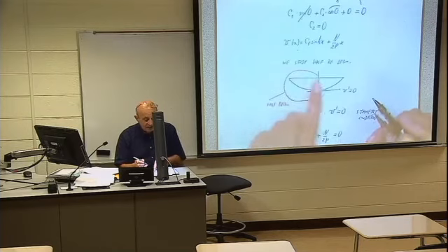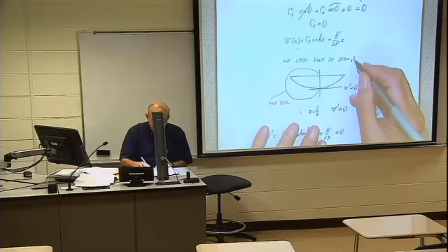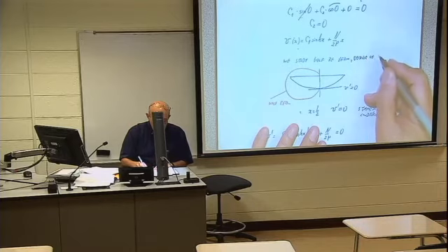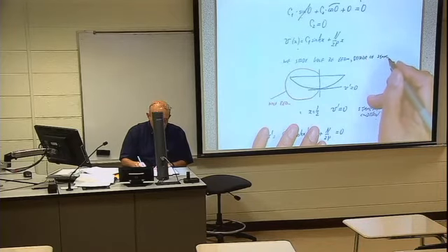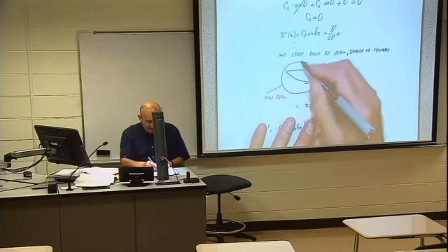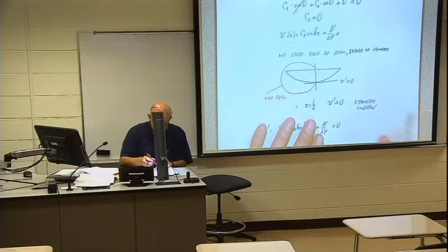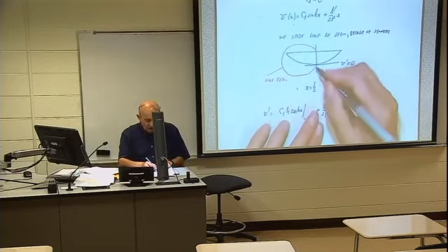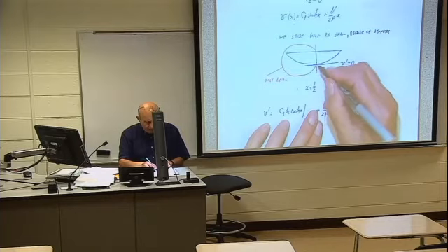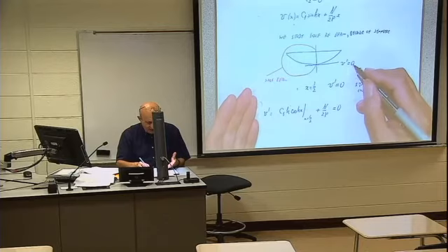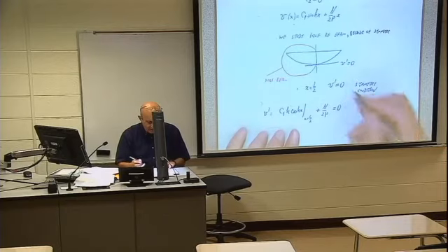Now we study the hinged beam because of symmetry. Okay, so that is the beam that we studied. So here, because of symmetry, there will be maximum displacement here. So V prime must be 0. At x equals L over 2, V prime is 0.